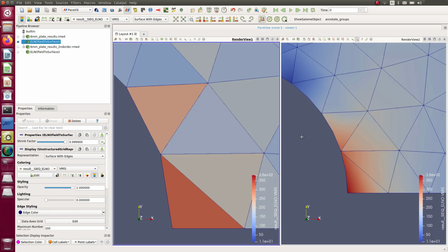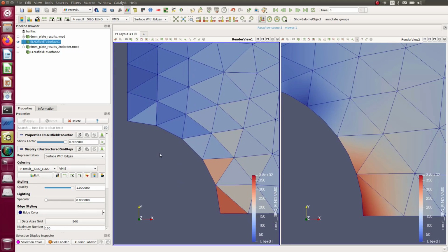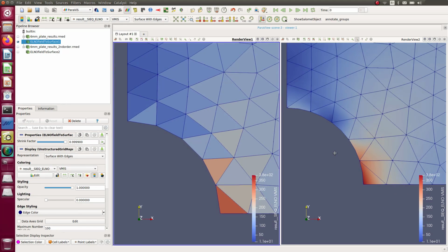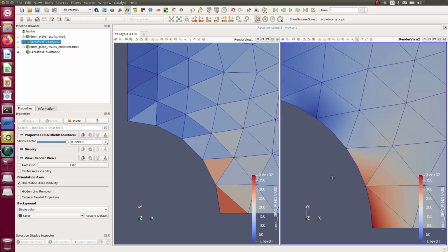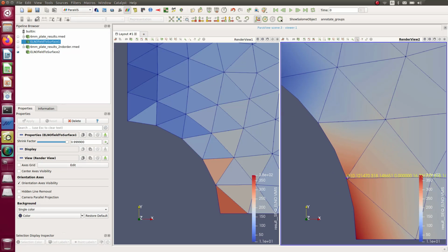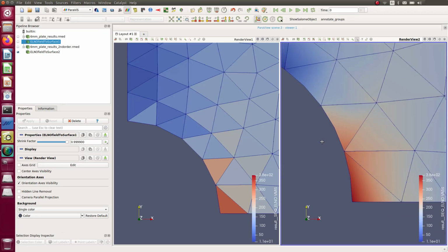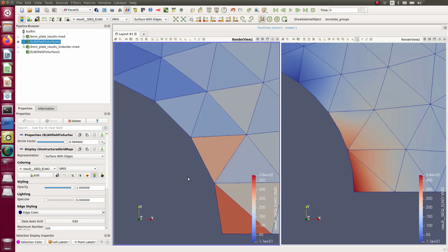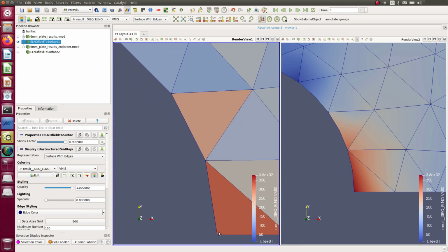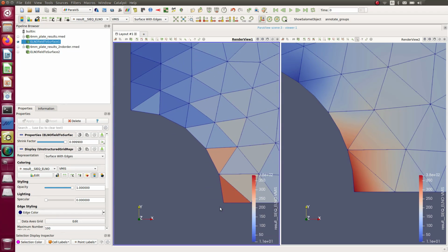The second thing we can see is that the approximation of the whole shape is much more accurate in second order, because this middle node is getting closer to the circle. It's deforming my triangle so that it goes closer to the circle shape. While in first order, of course, there's no middle node, so it's not possible to approximate the circle shape.